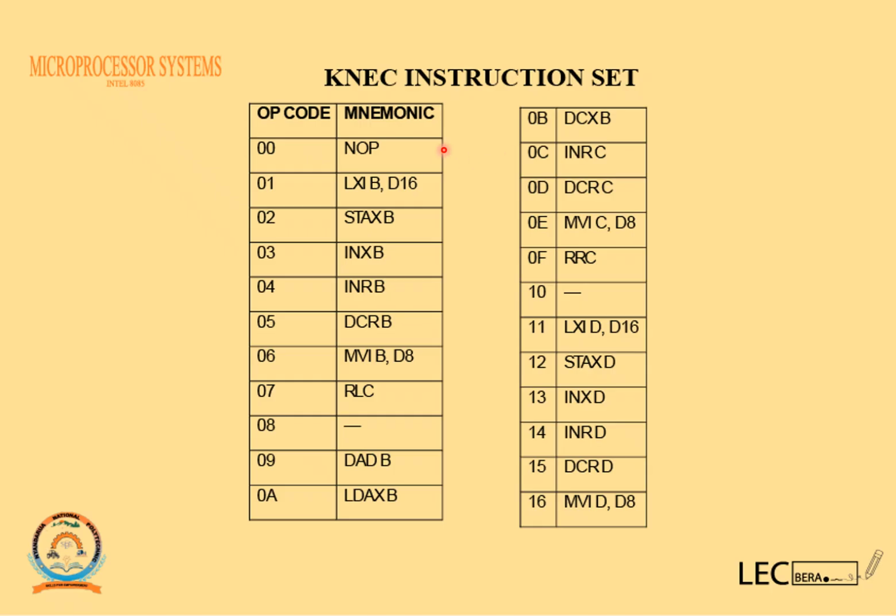So as I was saying, the instruction set at the back of the paper is categorized in opcode and mnemonic. So for example, I have a mnemonic here whereby I'm loading register BC as a pair with a memory address, which is actually a 16-bit address. So this one is a type of mnemonic code which is going to perform that function.